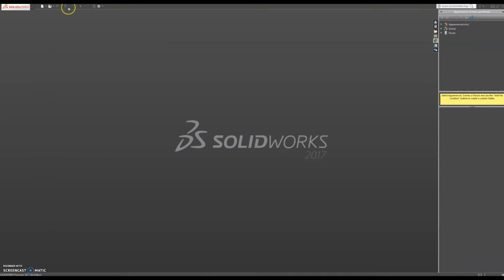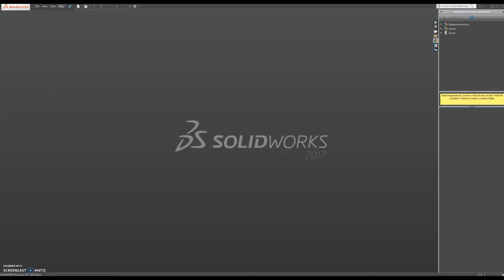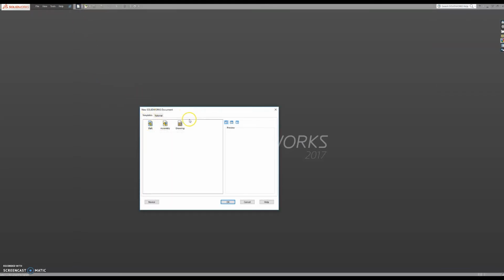And then once you get here, if you hover over this little black arrow that brings out that area, you can click it and pin it there if you need it, but you don't really need this area at the moment. And the gear icon, we will cover once we get into SolidWorks. So let's say you want to start a sketch. What you want to do is click on this little sheet page, paper icon. Once you have this, you can either choose assembly, drawing,